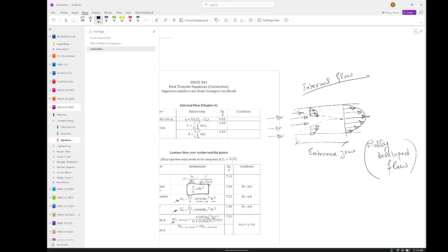Everyone understand? So why is it almost zero close to the surface of the conduit or pipe, whatever you want to say? Because at the surface, it is going to create the maximum amount of resistance to the flow, so it can't move. That's because of the boundary layer growing from the surface, right? In fluid class, you guys remember that, right? This could be a perfect example to understand this boundary layer effect, right?